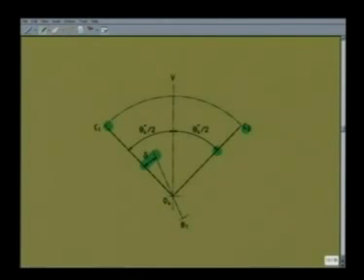So, let me pose a problem that modifies this design, but you are allowed to change only the crank length O2A, this coupler length AB and the angle delta to satisfy three requirements, namely the wiping field should be symmetrical about the vertical line O4B, and the width of the wiping field, that is the horizontal distance between these two extreme positions E1 F1 and E2 F2, is say 450 millimeter to the same scale, and there should be no quick return.